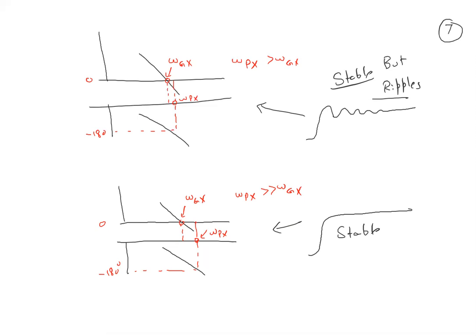That's why we define a terminology known as phase margin, that we need to give some margin between these two quantities. And how do we decide this? Based on, again, the loop gain. So we use the loop gain and we put some margin in the loop gain. If I want to decide what my phase margin, PM, is, it can be anything, but I will tell you what is a reasonable value.